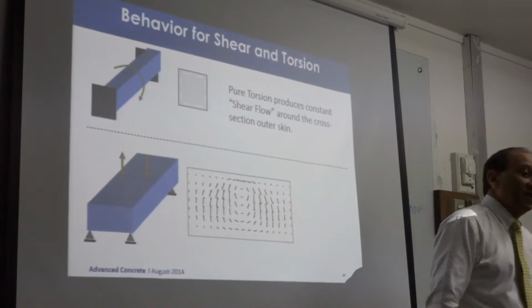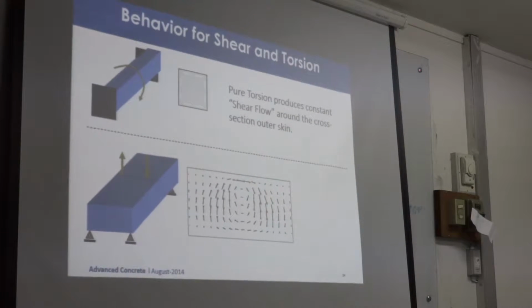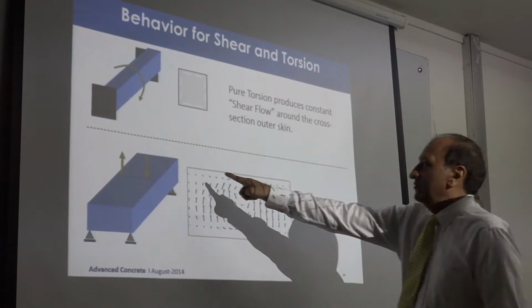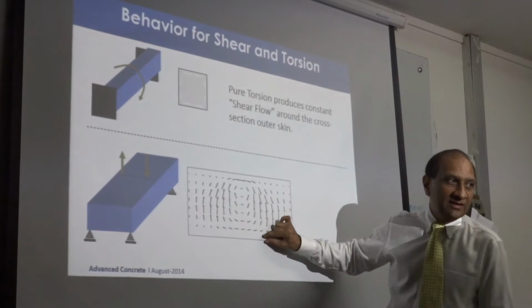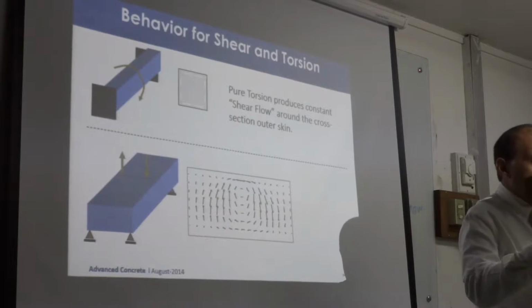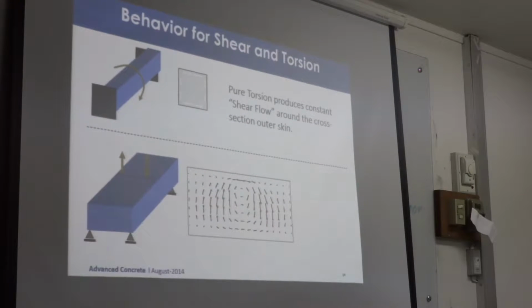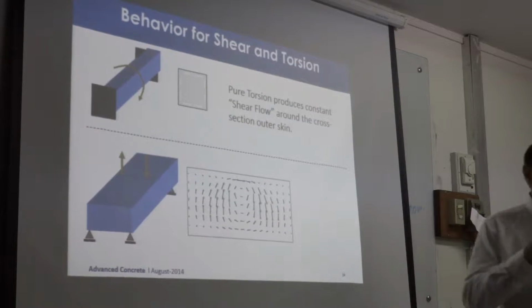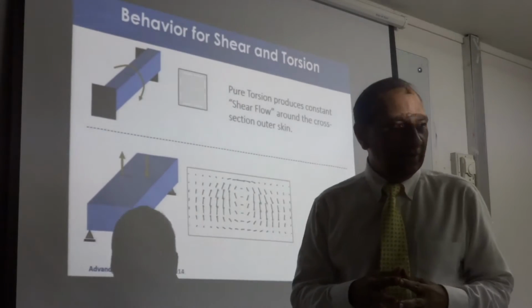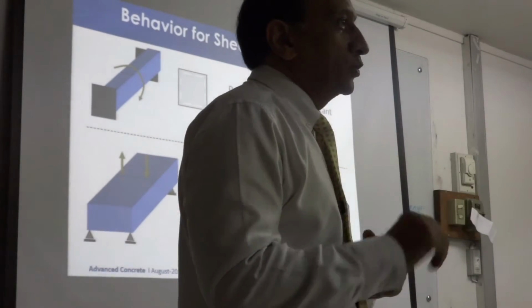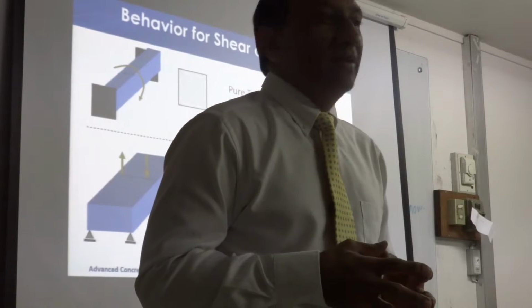And that already saved them enough money to reduce the cost a lot, because this is very long, 5 meter. And if you save the reinforcement 5 meter here, 5 meter here, 10 meter long reinforcement, every 100, 200 millimeter for 12 meter long, you can imagine it's a lot of reinforcement multiplied by 1,000 of these. So hundreds of thousands of tons of steel was saved only because we are able to separate clearly the torsion and shear behavior and corresponding reinforcement. So a small change in detail can mean millions.